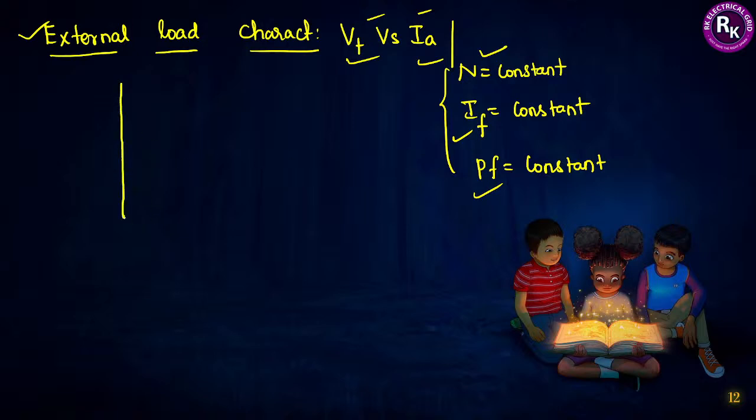Now let us build the characteristics, that is, the external characteristics of the alternator. If you observe, it has been drawn between armature current versus voltage V, as I told you. So initially it will start at E. V will be equal to E. E and V are both equal when the armature current is 0. After that, they would form a straight line, but due to the practical characteristics of the alternator, it will not follow a straight line. When I continuously increase the armature current, based on the nature of the regulation and power factor, these characteristics will droop.